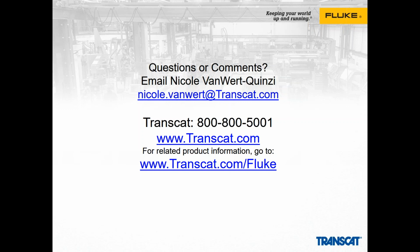And there are standards which dictate what is allowable, but sometimes you may get a fault in a piece of equipment, maybe a filtering capacitor fails on the equipment, so that can cause extra distortion. Or it may well be that the manufacturer is not that reliable a manufacturer and they haven't really taken measures to ensure that the device is filtered properly. So that often depends upon the cost point of the price of the equipment, to be honest.